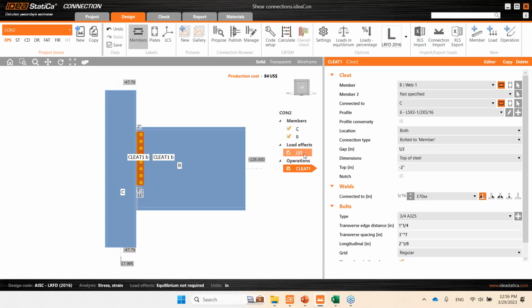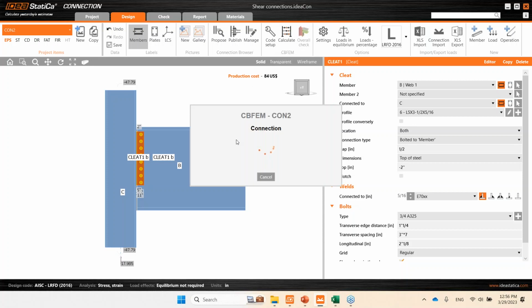and look at the deformed shape, you could see the beam actually moving upwards for a vertical load, for a gravity load, so vertical load going down. So that could tell you that something is actually off with the way the analysis was run. So it could be more conservative, but it could also be plainly wrong, depending on the scenario, of course.